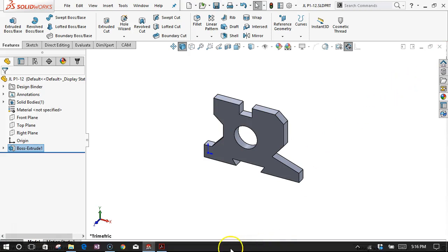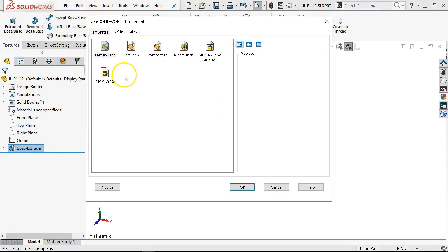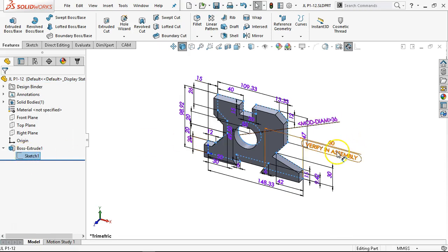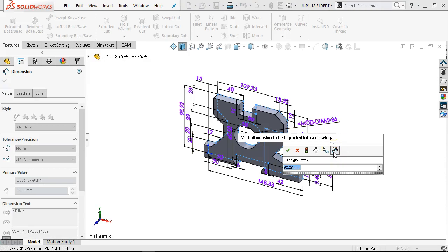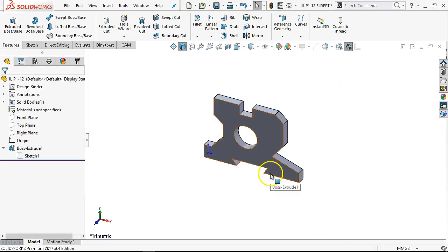All right. One question on that. If you go ahead and you find you want to change that dimension, can you show again how you go to that stage where it looks like that extruded and go back to open up the same sketch, not a new sketch? Okay. So the quickest way, if it's just one dimension, you're not going through and doing a lot, is to double click, and double click. And maybe we decided that was 55. All right, that does not update instantly. We have to rebuild. And then I will see that go from 60 to 55.